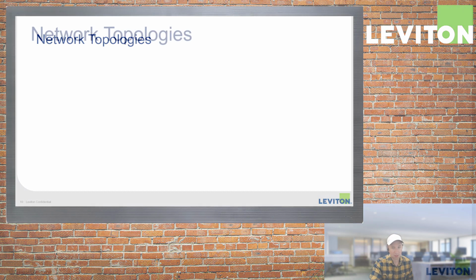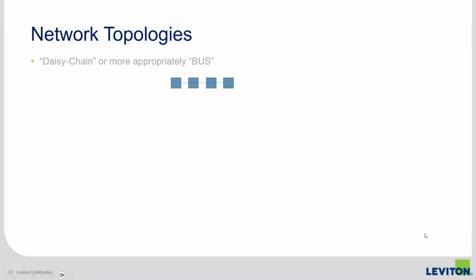So let's look at some network topologies. I mentioned earlier that the LumaCAN network is a daisy chain network. Some people think a better term for this is bus, and I could argue either way. But in our case, we call it a daisy chain because it's a chain of devices that are all connected together. Every device has two RJ45s on it, one for the incoming and one for the outgoing wire, and it doesn't matter which one you connect to each jack, just connect one to both. And you connect them in a long run, so there's no T's, there's no splices, there's none of that. One continuous chain of devices.